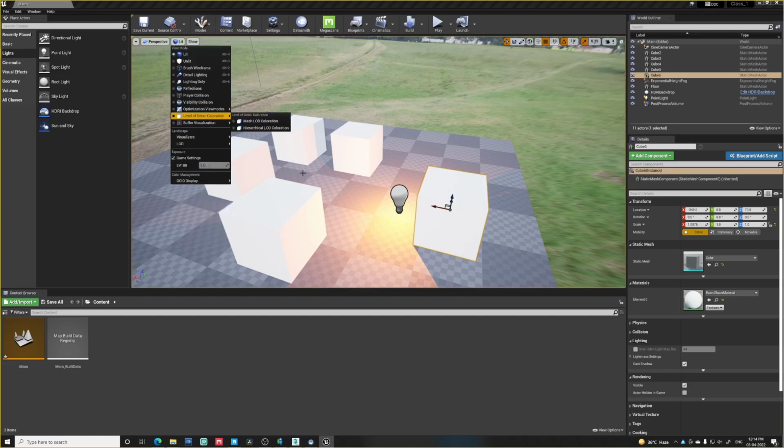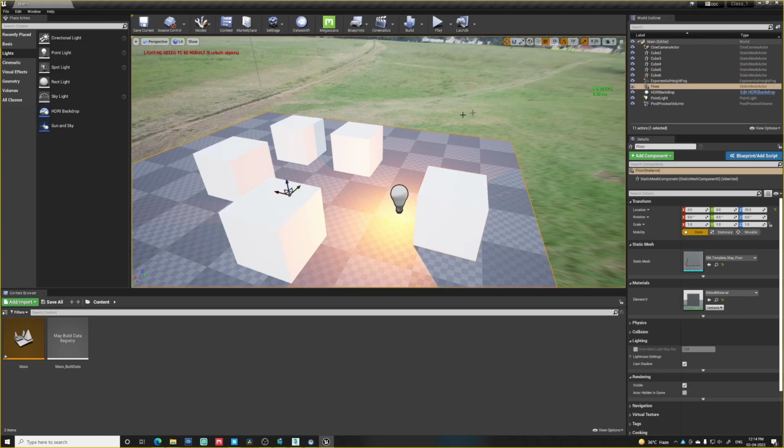So this panel is also not useful. You get this shortcut key WER just to rotate and scale. The same thing is here. You can just select it from here. And this is our pivot to change the world space to local. You can just change it. This is world, this is local.